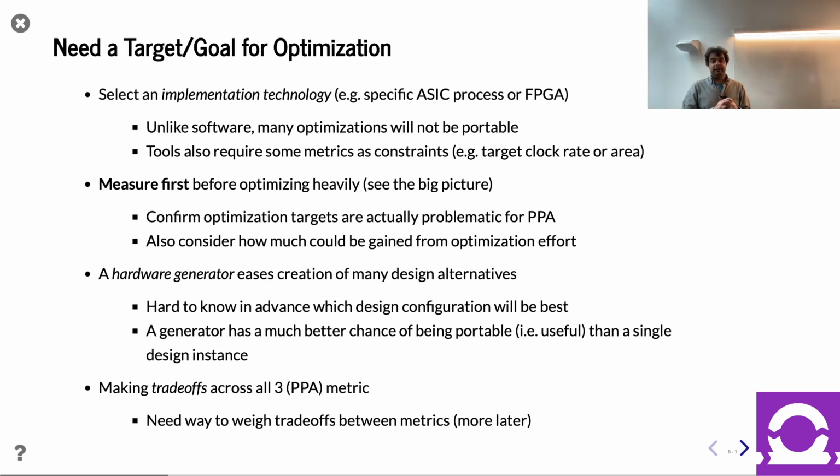That being said, a few points to note. One, I'm very familiar with the internals of the Scala-based backend flow using FIRRTL, referred to as the SFC, the old version. The new MFC, which is part of Chisel 5, Chisel 6, uses a different set of code. I believe that technology in there, because it's somewhat derived from LLVM, may have a little more sophisticated optimizations. If not now, hopefully in the future.